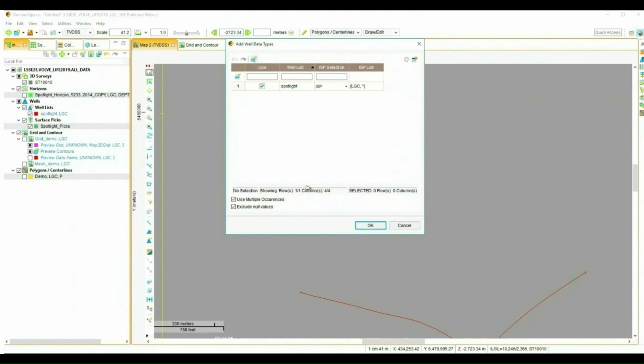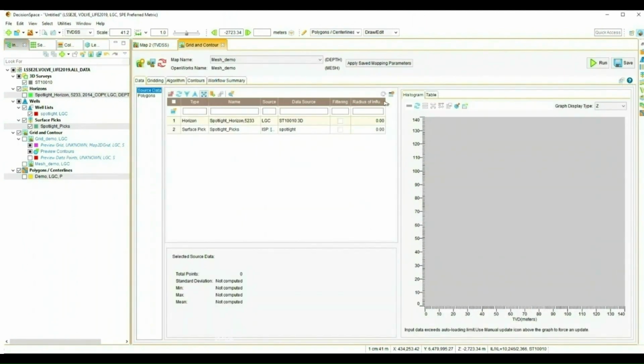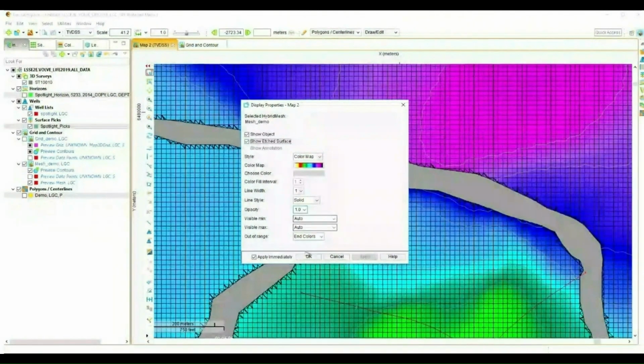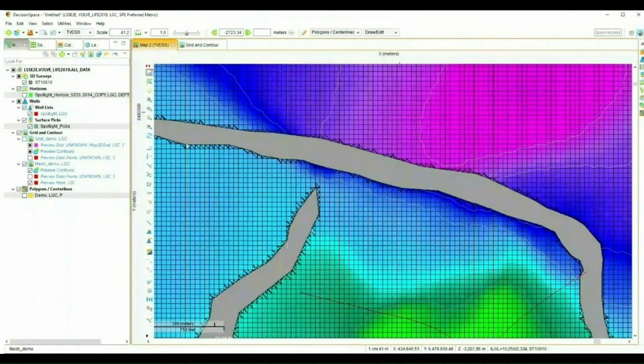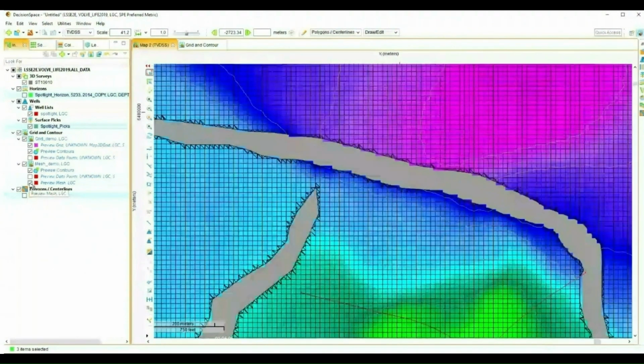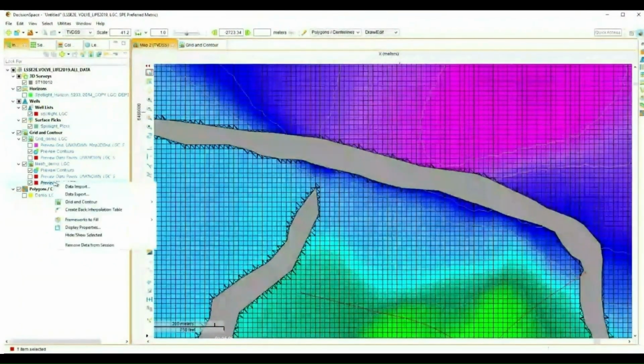If we generate a mesh output from grid and contour, we can see that the hybrid mesh has smooth intersections with the included fault polygons, and this can be best shown through the display options, where an etched overlay displays the surface edge, where intersections between the hybrid mesh and polygons are shown by triangles. We can take a look at how this compares with traditional grid outputs. Grid outputs display stair-stepped artifacts, which can sometimes miss data out when intersecting with polygon boundaries.